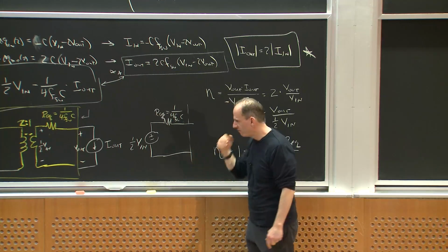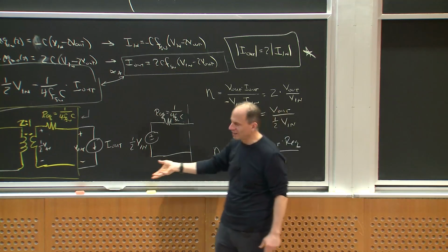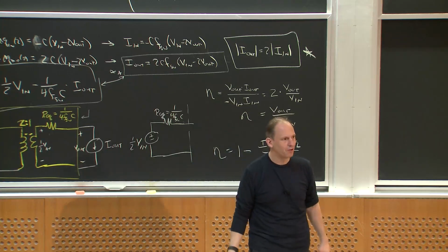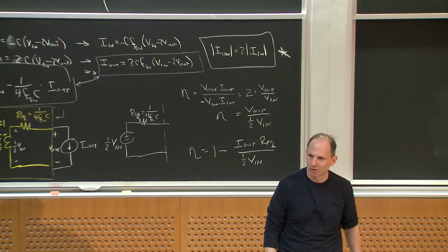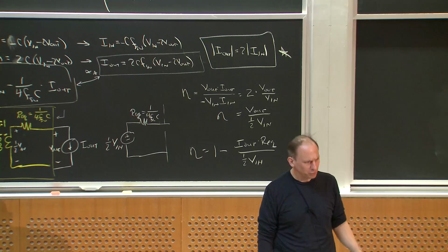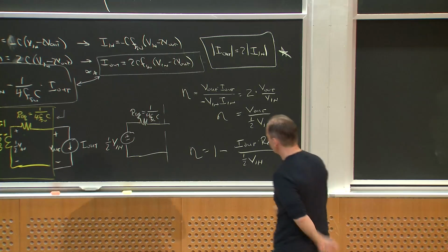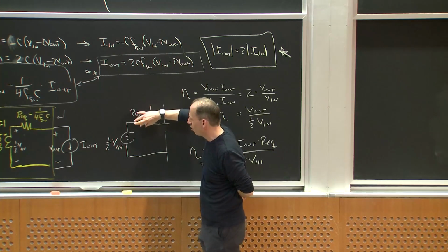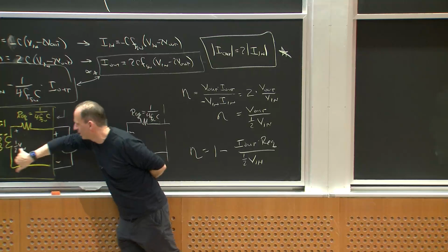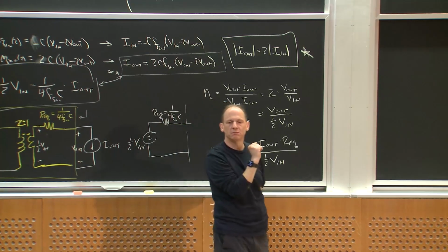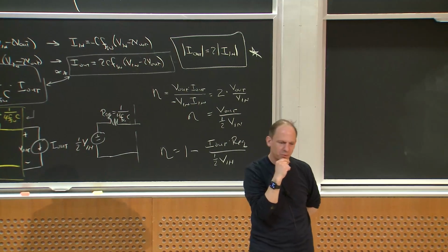Okay? And in fact, people would call this thing a 2-to-1 step-down switch capacitor converter. Why? Because they're thinking of the voltage, right? Ideally speaking, if I make this resistance really small, I'm really just doing sort of like an ideal transformer, 2-to-1. Okay? And so people would call that a 2-to-1.